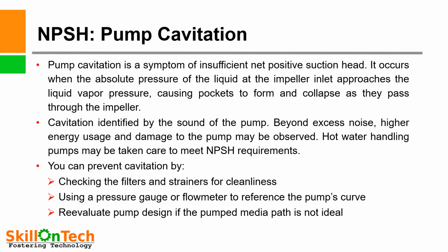So, when these bubbles burst, a heavy impact on the impeller discharge face will occur and that will damage the impeller. Cavitation is identified by the sound of the pump. When the pump is under cavitation, you can hear a heavy sound beyond excess noise, and higher energy usage and damage to the pump may be observed.